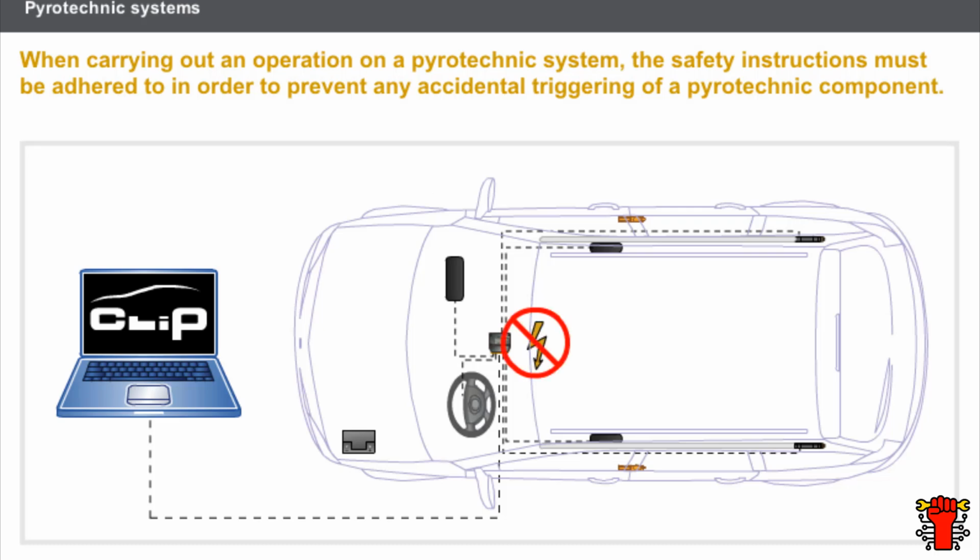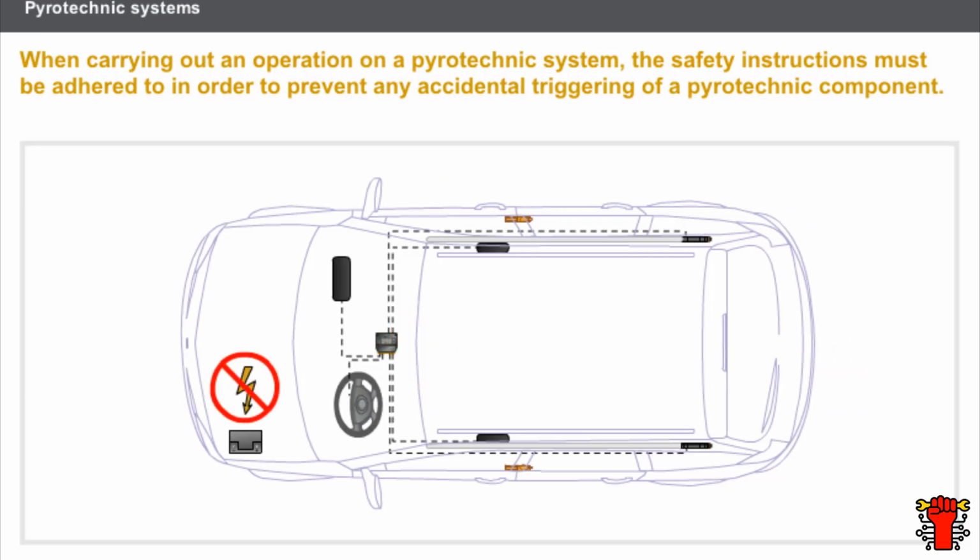When carrying out an operation underneath the vehicle body, it is essential to lock the airbag computer using the diagnostic tool and to switch off the ignition. The battery must be disconnected when replacing a pyrotechnic component.